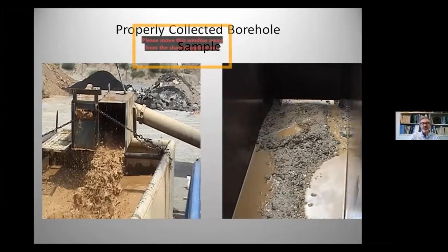As a geologist, many of us have been out on sites trying to characterize these sediments as they're coming up out of the hole. So we want to look at these cuttings and samples, looking at the texture, seeing if they're igneous, metamorphic, or sedimentary. Basically just trying to glean some evidence to see if they have the capability of transmitting water, or if they are from a water-bearing zone or perhaps a compact formation that's not going to give us much water.